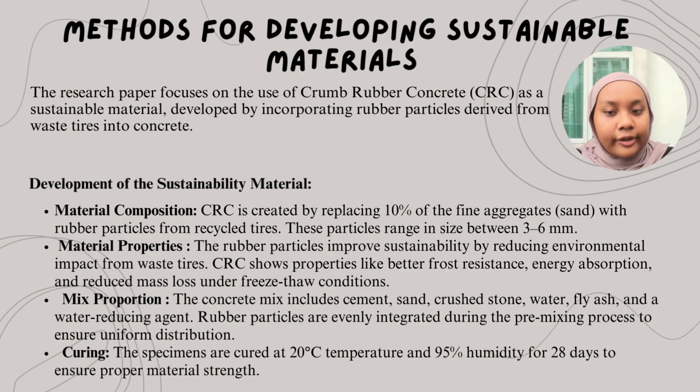Number four, curing. The specimens are cured at 20 degrees temperature and 95% humidity for 28 days to ensure proper material strength.